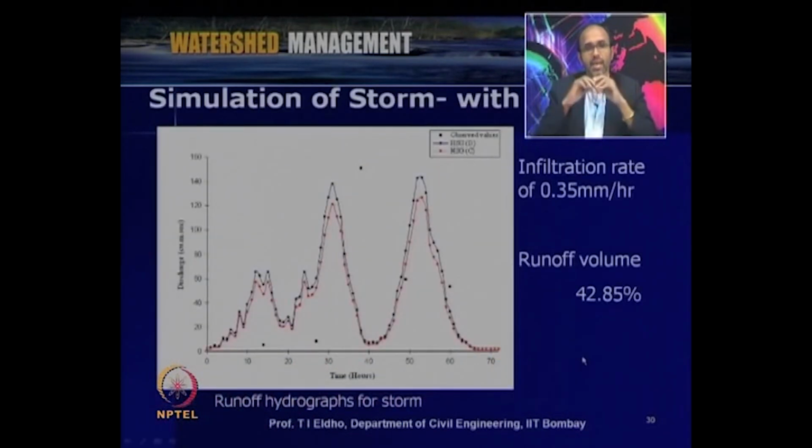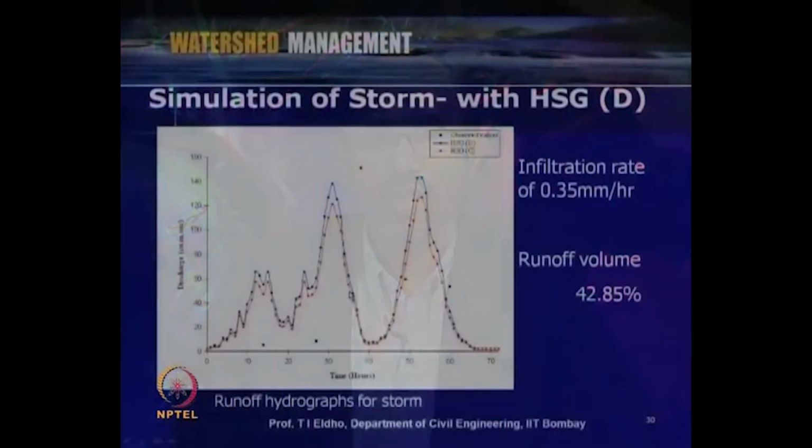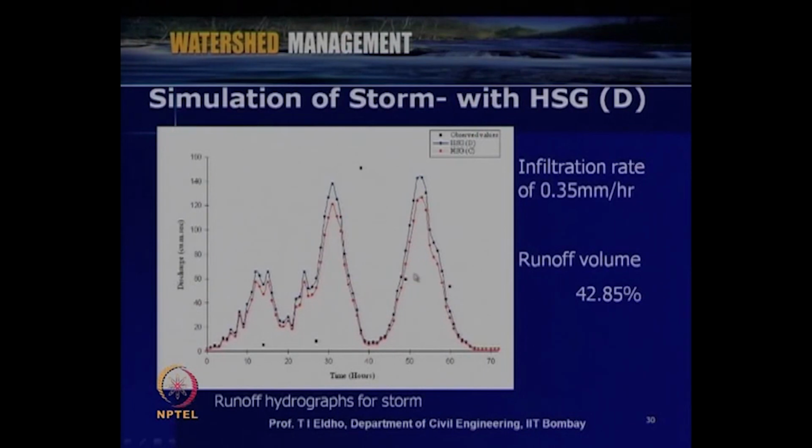Then, as I mentioned, we use the SCS-CN method where, for some of the rainfall events, by using the detailed elevation model and various maps, we have run the model to obtain the runoff. This shows the discharge versus time. Here the rainfall data details are not given, but the main purpose of this case study is how we can effectively utilize geographic information system to produce various maps, various data sets for hydrological modeling. So, that was the purpose.